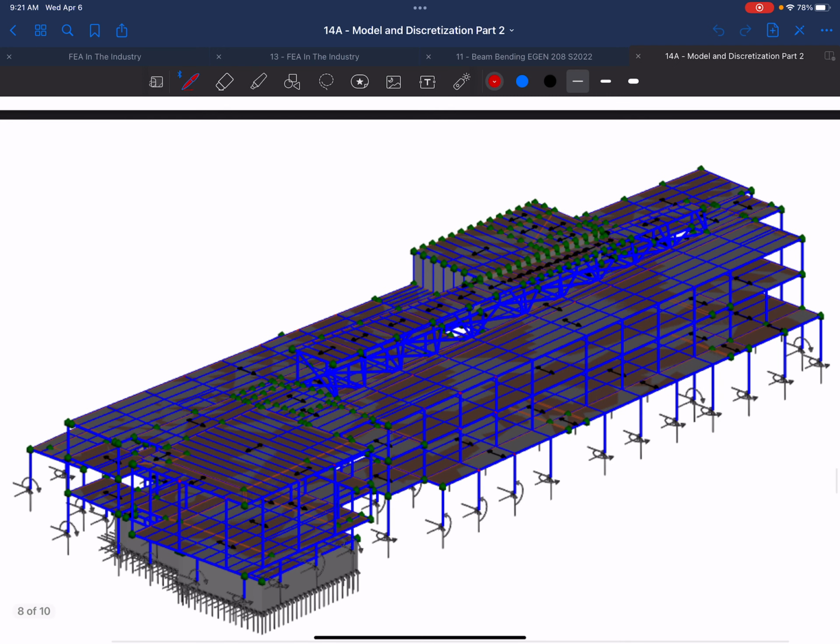And in VA, you can go a step further. Once you have this, in each one of those design groups, you can say, all right, I want to design this. You go in with a guess, and you could limit it and say, all of these members, I want to make sure that they're not deeper than 12 inches, and that they're wide flange sections. You hit go, and it gives you the top 10 best members with respect to unity values based on the bracing that you decided to use and all of the design checks that you gave it. Then you can select one, implement it, and it dumps it in.